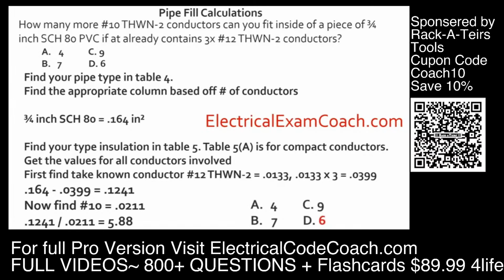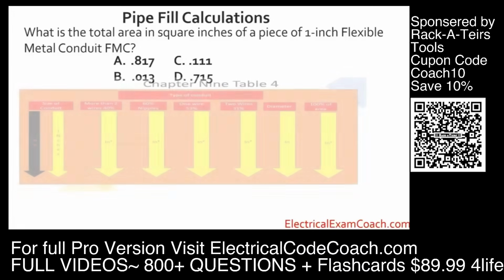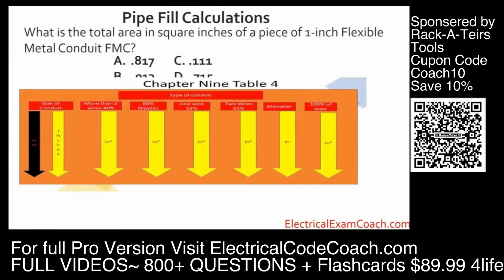Great job. What is the total area in square inches of a piece of 1-inch flexible metal conduit? For this one, we're going to head straight to Chapter 9, Table 4. When we get there, we're going to verify that we're in the right type of conduit.